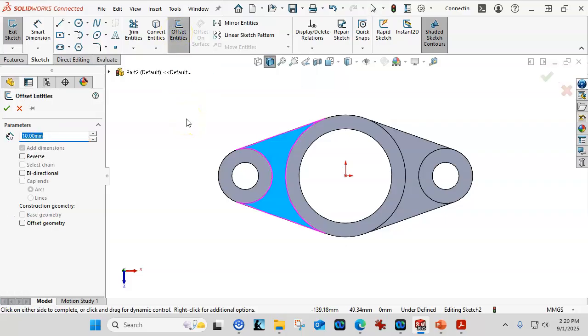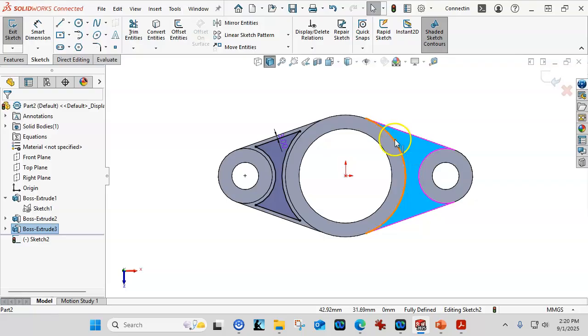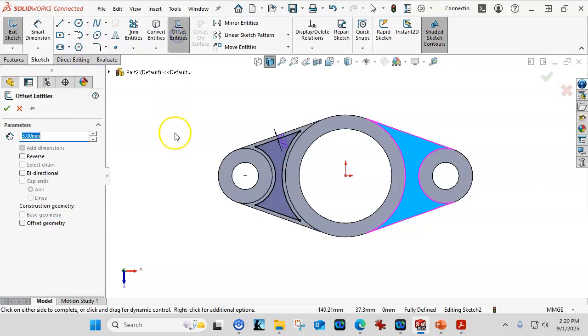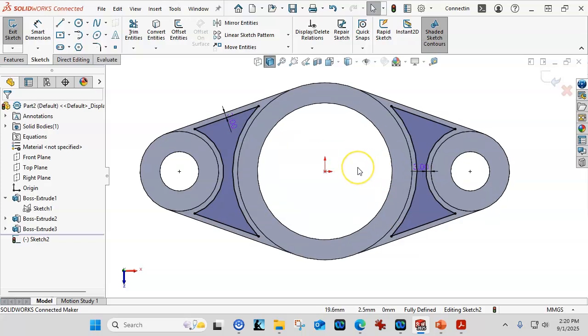Thickness all around is 3 millimeters, and it's not going to show the preview until we do something like that. We can only do one face at a time, so we're going to add both of these. I could mirror this over, but I think it's probably going to be about as easy to offset and reverse and go ahead and hit OK. If we were just to extrude this, I could probably do the fillet. It's 8 sketch fillets or a couple of selections on the feature fillet, kind of a toss-up, but we have 8 times 3 millimeters all the way around.